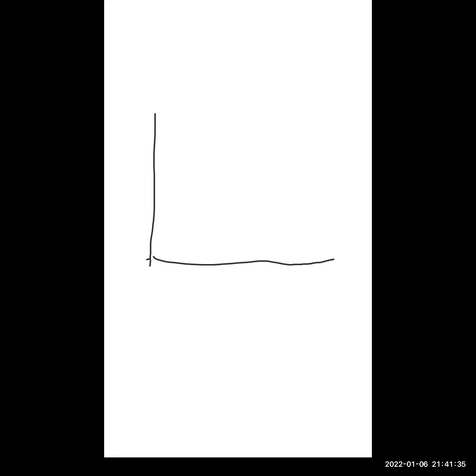Say a rubber band is there. We all know that when we deform it a little bit, it will return back to its original position, and then as we increase it, it will again return back to its original position. After a certain amount, it will not come back to its original position. It will go to a new resting length. That is a second zone. But basically, what we will be seeing is up until the breaking point or the yield point comes, the greater the amount of force you exert on a spring, the greater will be its deformation. The greater the deformation, the greater will be the force with which it will be pulling us back.